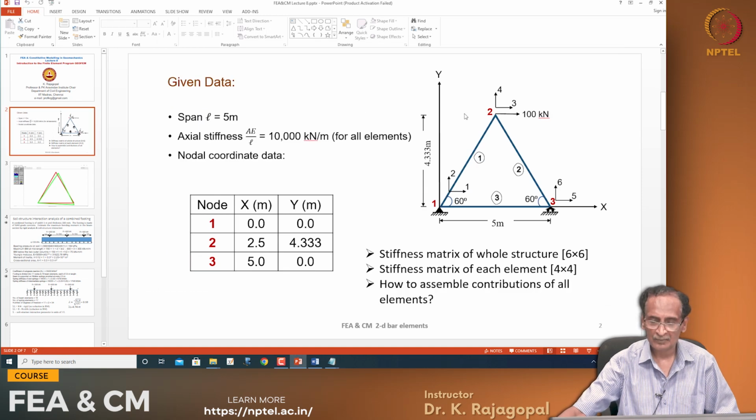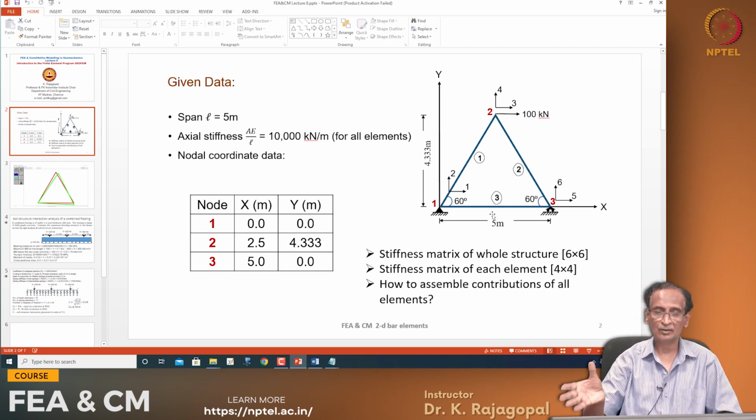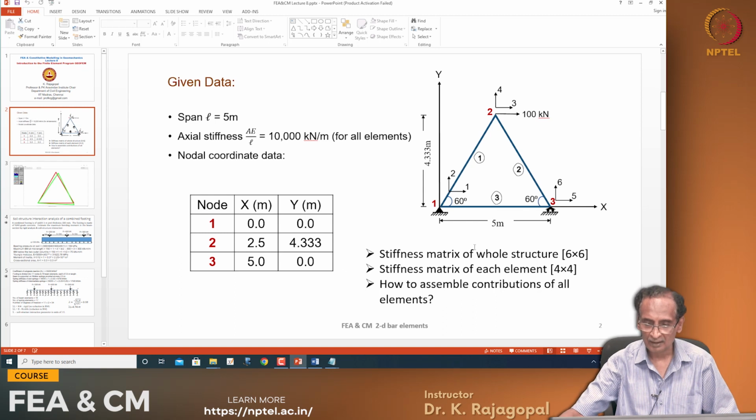It is basically counteracting the applied moment. So actually we are applying a force of 100 here, and the reaction force, as we have seen, is basically 100 times 4.33 by 100 times 5, which is your external moment, and the couple is the reaction force multiplied by 4.33.